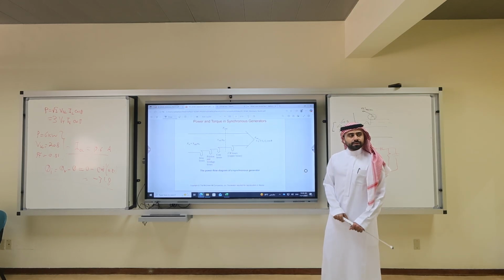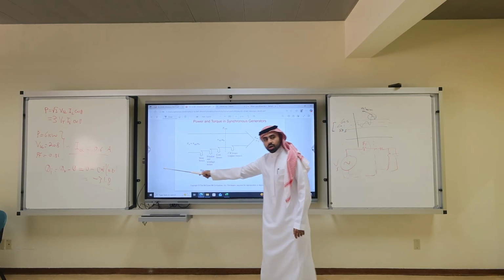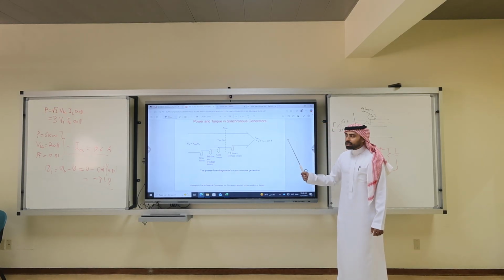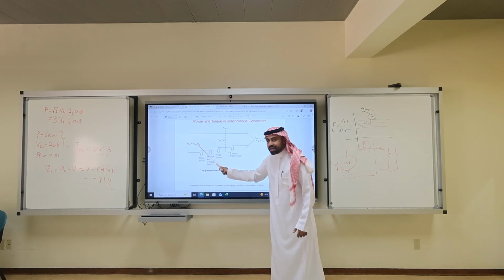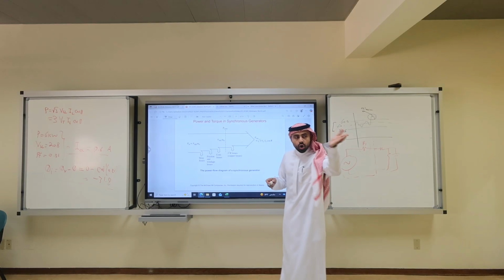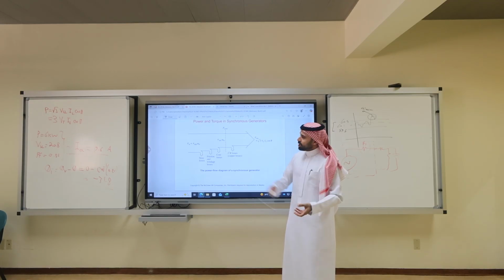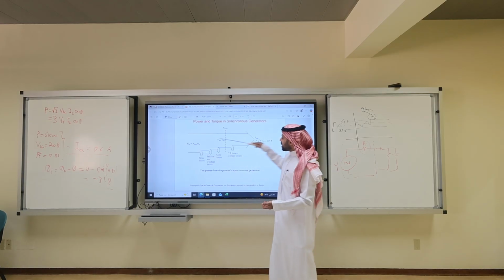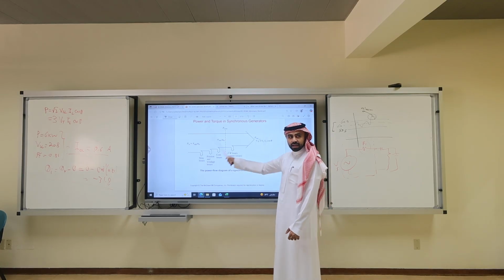Do you remember this curve? For an induction motor, what was my input? Electrical. What was my output? Mechanical. Here I flip it. Here my input is mechanical torque times speed, omega m, which is very close to omega sync. Very small difference. You cannot have exactly synchronous speed, but if it's 1800, maybe it's 1798 RPM. You can say it is roughly omega sync. What are the losses? The stray losses and friction that were on the right are now on the left.